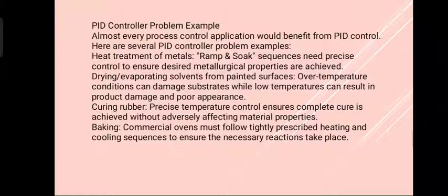Heat treatment of metals, ramp and soak sequences need precise control to ensure desired metallurgical properties are achieved. Drying or evaporating solvents from painted surfaces. Overheating temperature conditions can damage the substrates, while low temperature can result in product damage and poor appearance.